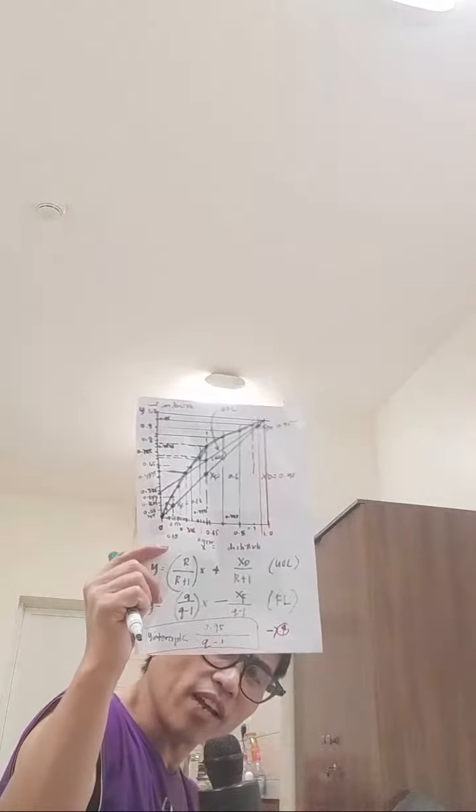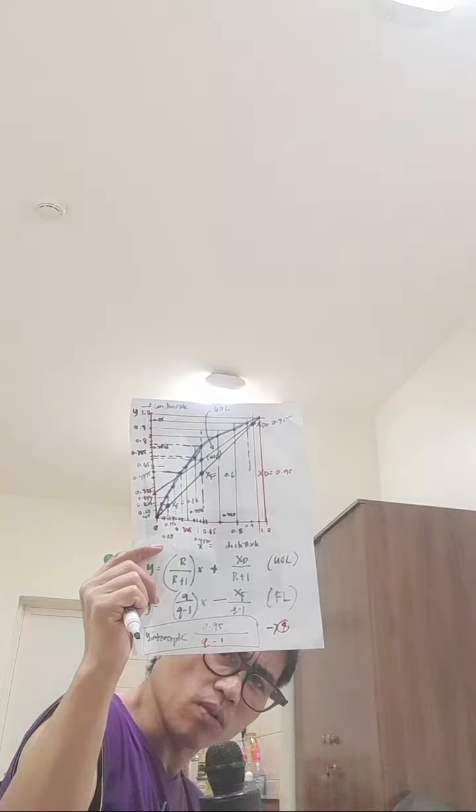So we need to get the angle of inclination from the horizontal line for the intersection of the upper operating line so that we can connect that to the XW. Okay? Something like that. The rule is that the XW connects to the upper operating line. Okay? In the Q. So after getting the angle of inclination, we have the Q. Okay. Now, so tangent theta,